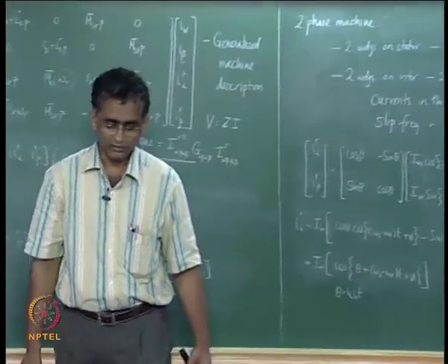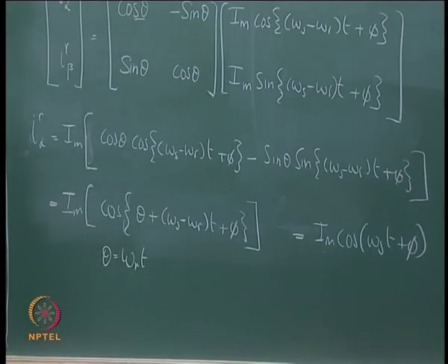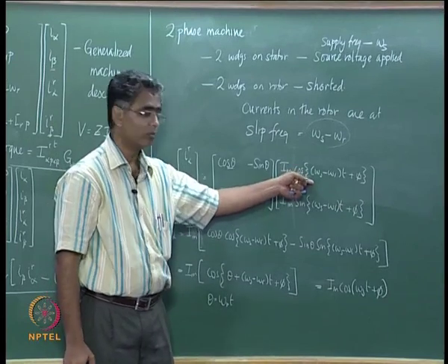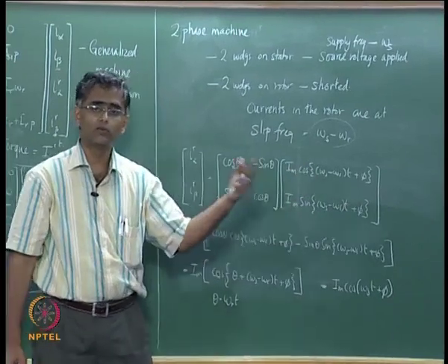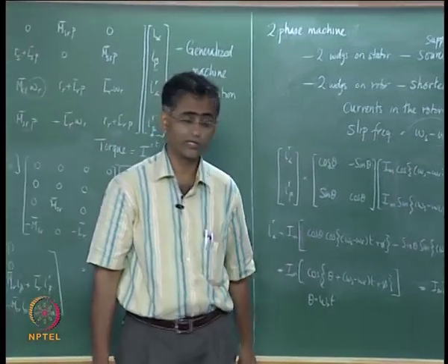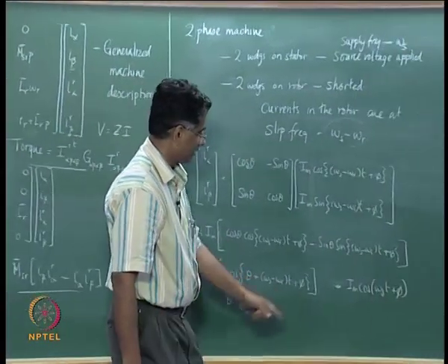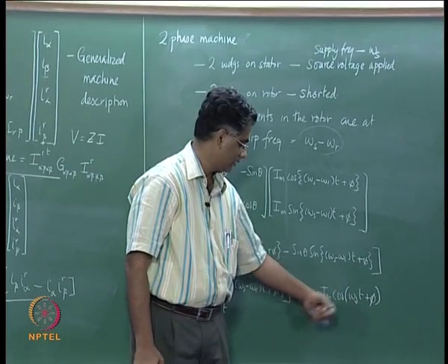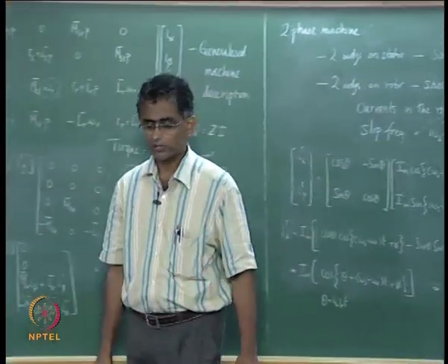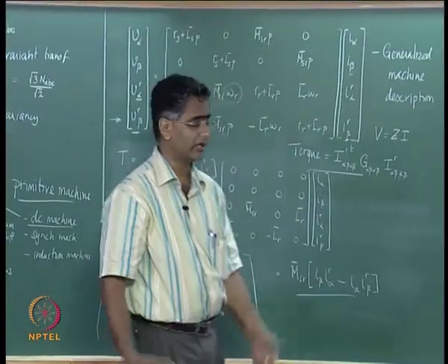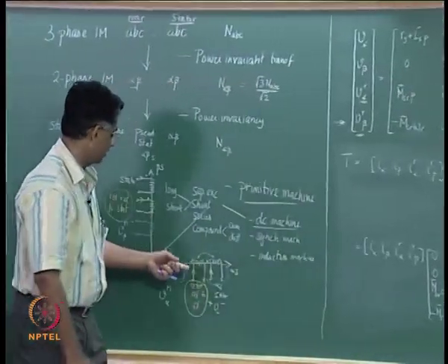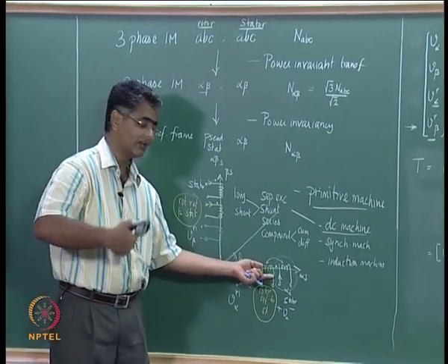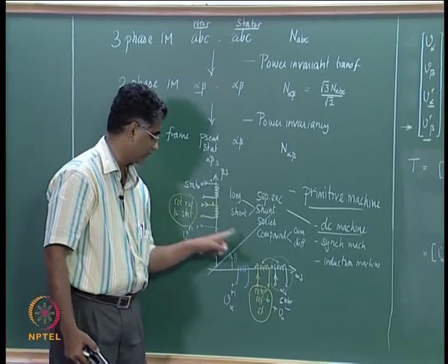This is interesting because what it says is that slip frequency currents that are flowing in the rotor, when you look at the flow of current in the pseudo stationary stator referred axis, now look like the supply frequency current, right. This is intuitive to understand, because we are looking at the MMF that is equivalently generated by currents flowing here.